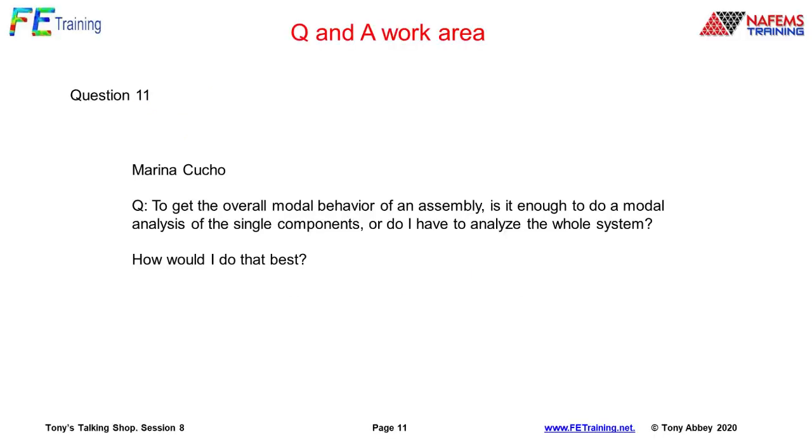Marina says, to get the overall modal behavior of an assembly, is it enough to do a modal analysis of the single components, or do I have to analyze the whole system? How do I do that best? Really, you've got to put the assembly together, and then it's the dynamic interaction between the components that is going to give you the overall assembly